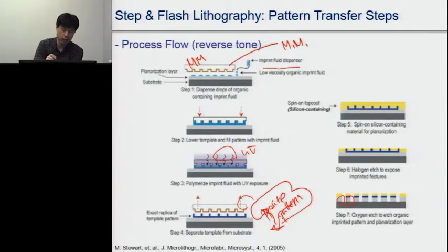So once we have this blue resist pattern, we spin coat another layer, this yellow resist layer, and then we do the dry etching. So roughly we etch at this interface, and then upon this interface of the etching, we just change the plasma, and then we just do further etching.